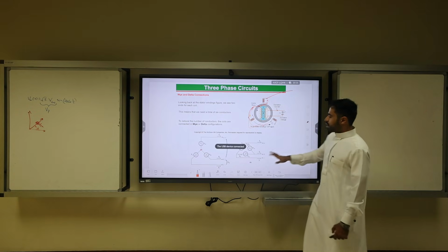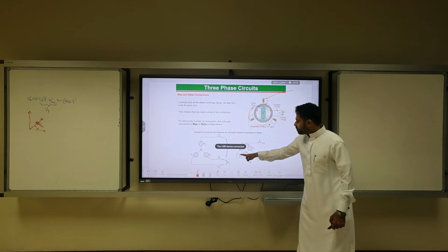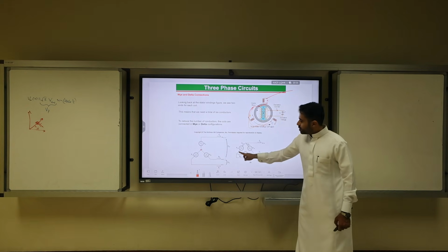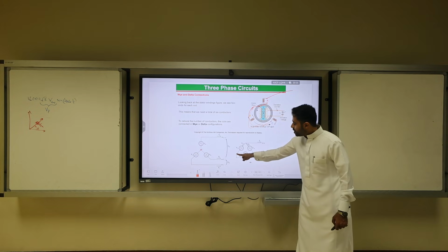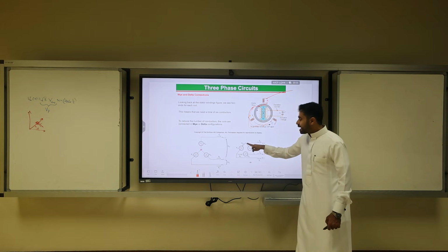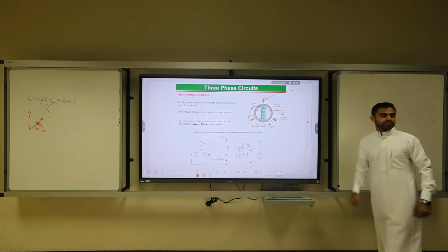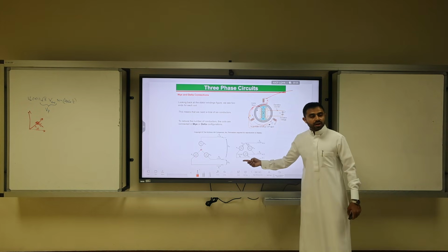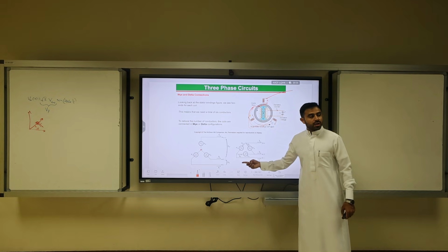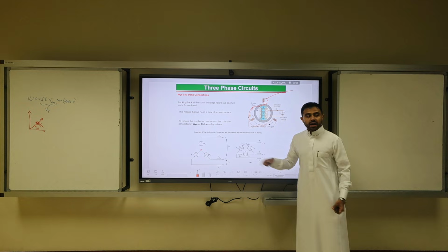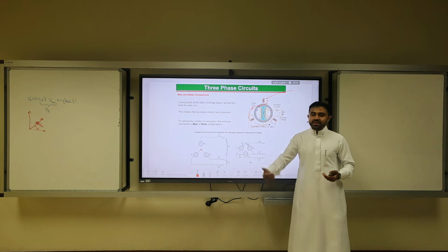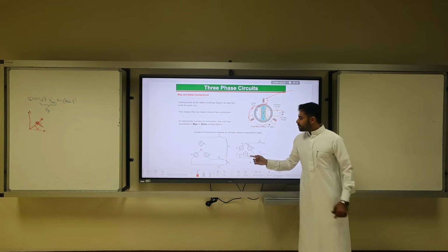Anyway, the delta connection, you connect them as a triangle. The positive is connected to the other, and then from every junction you take a cable outside. One major advantage of delta connection, it blocks what? The harmonics. Harmonics are 120 hertz, 180 hertz, multiples of 60 hertz.